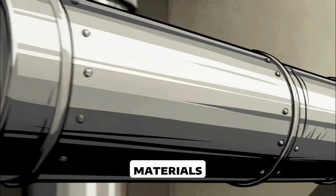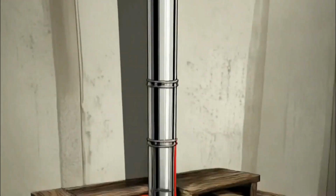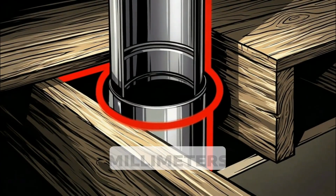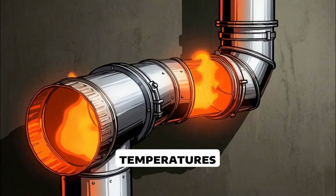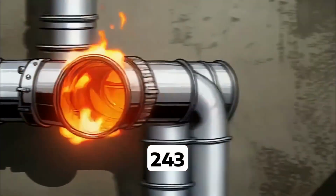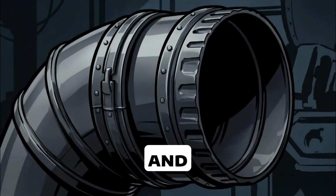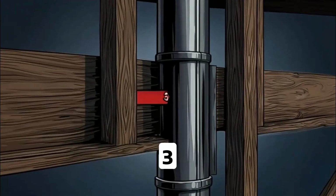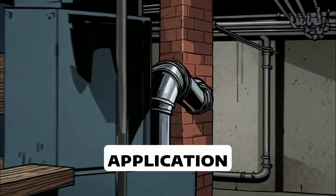Now, vent materials. Type B vent is commonly used for gas appliances. Typical minimum clearance to combustibles is 1 inch or 25 millimeters. Many Type B vents are approved for flue gas temperatures up to 470 degrees Fahrenheit or 243 degrees Celsius. Type L vent is heavier duty and often used where approved. Typical minimum clearance may be 3 inches or 75 millimeters depending on listing and application.